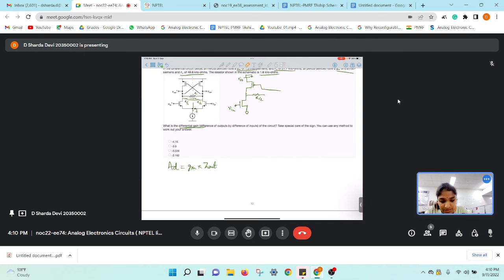Rather than connecting the gate of the same PMOS with its drain, the gate of first PMOS T1 has been connected to the drain of T2, and the gate of T2 has been connected to the drain of T1. When we are biasing, both sides will have the same amount of current, and since both transistors are matched, it is equivalent to the diode configuration of a transistor in itself.